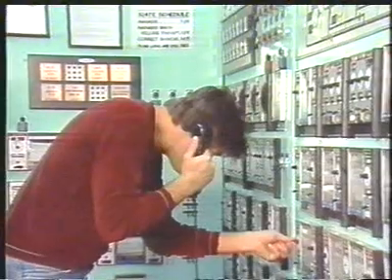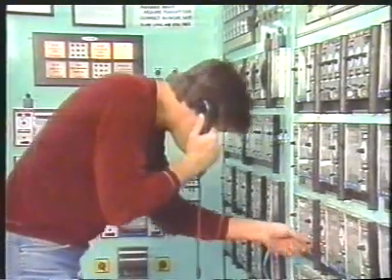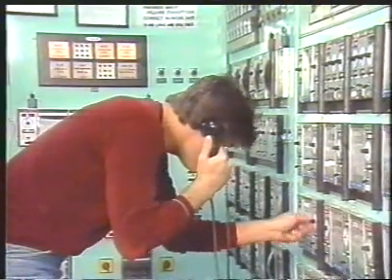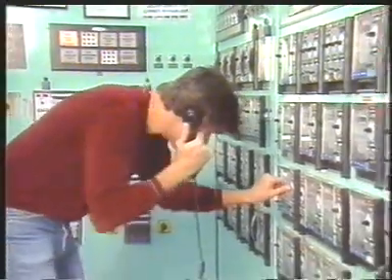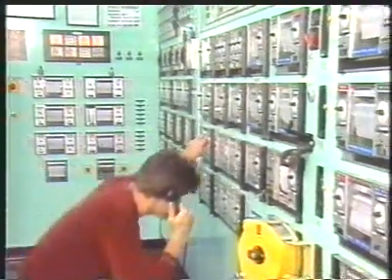By cutting off the fuel and removing as much heat as possible, you minimize the chances of furnace damage. Once the situation stabilizes, you would want to call in maintenance and have the defective pump repaired.